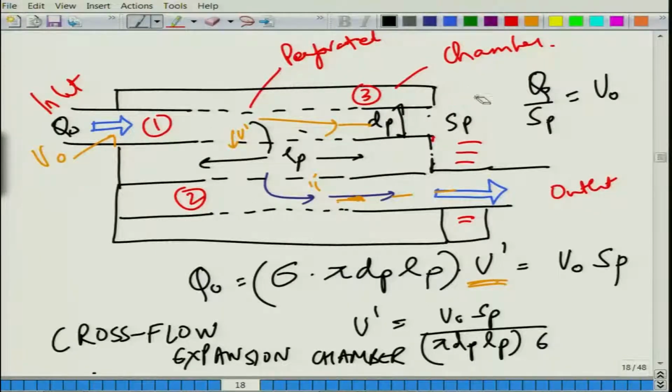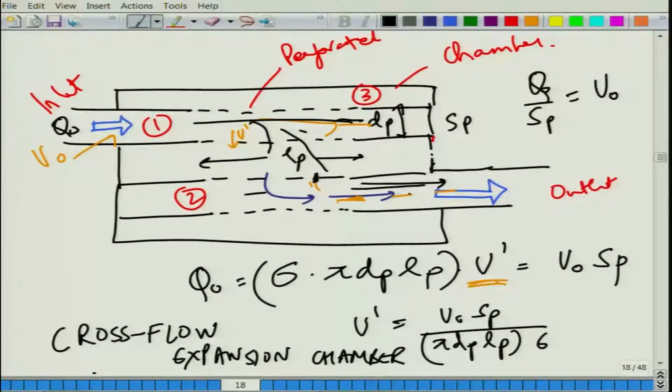Suppose this guy is not there, it is a closed cavity. So, this will be 0 here, going from the maximum value to 0, and in the process your bias flow will be non-zero here, entering this perforate, and you will have some non-zero convective value in the central duct as well, which we have conveniently ignored. Then we will be picking up from 0 value here to a maximum value in the outlet duct. So, the idea is that the flow is gradually varying.